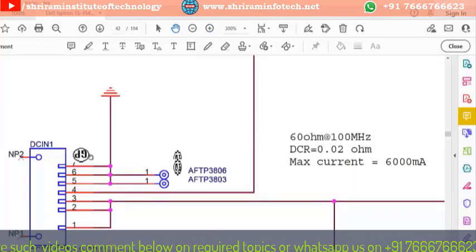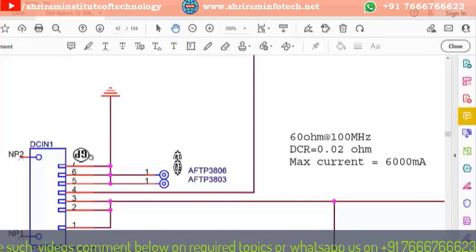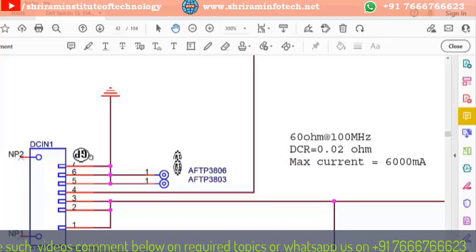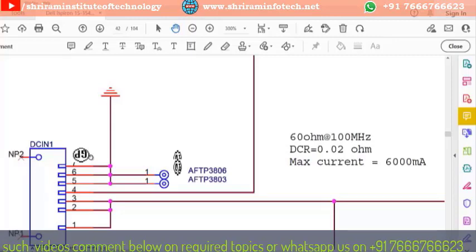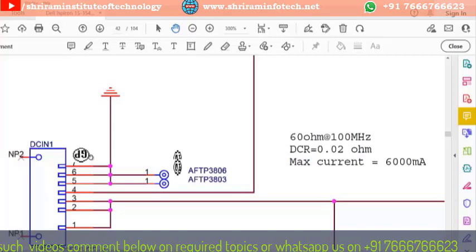Normally in a Dell laptop, the adapter has 3 pins. One is positive, another is negative, and the third is the adapter ID, also called the PSID, where the adapter informs the SIO how much wattage the adapter can provide. This is only on Dell and HP laptops. Lenovo and other laptops do not use this adapter ID or PSID signal.